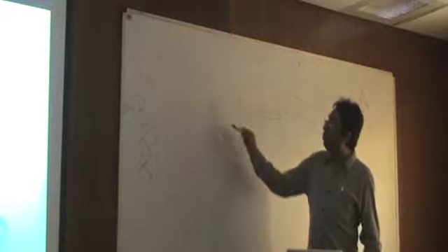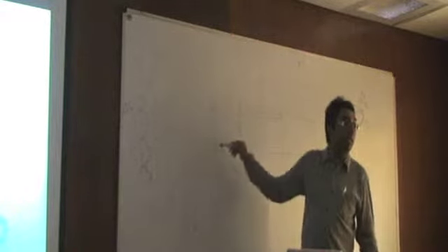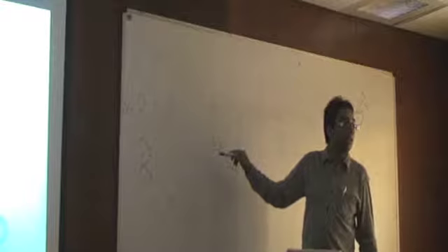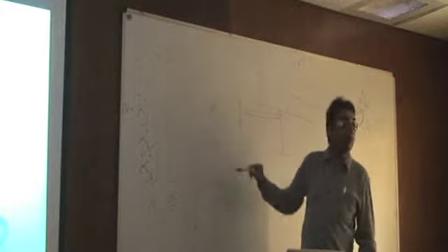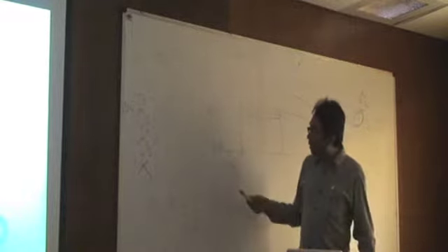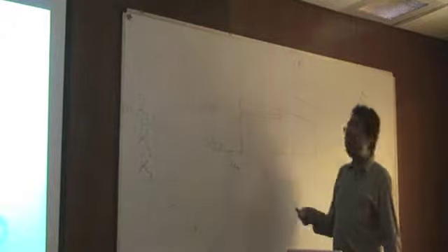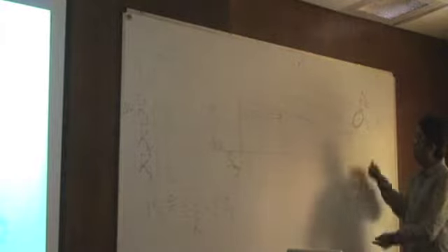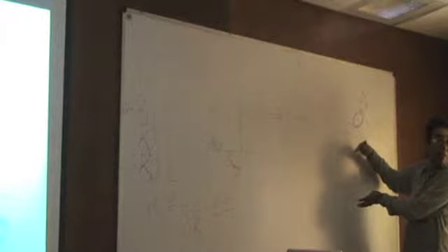Where is that effect observed? It is in the cross-section analysis. That's why the cross-section analysis is getting affected. So it's basically these terms that are going to get affected. But how does it actually come into the picture? It's because of warping. What is happening is that it is no longer a rigid body-like motion that is taking place.